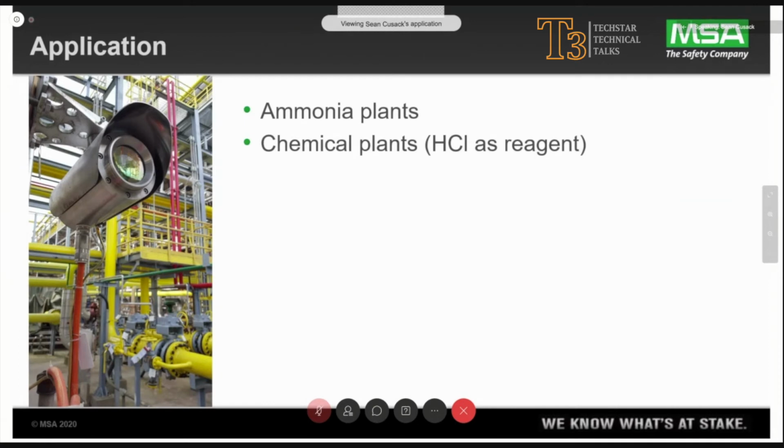Okay. Do detectors have crosstalk interference? Is positioning important when using multiple systems? Positioning is important because you want to make sure they're staggered. So if you have a line of them along a rack and they're right next to each other, you want to make sure that the transmitter and the receivers are opposites.